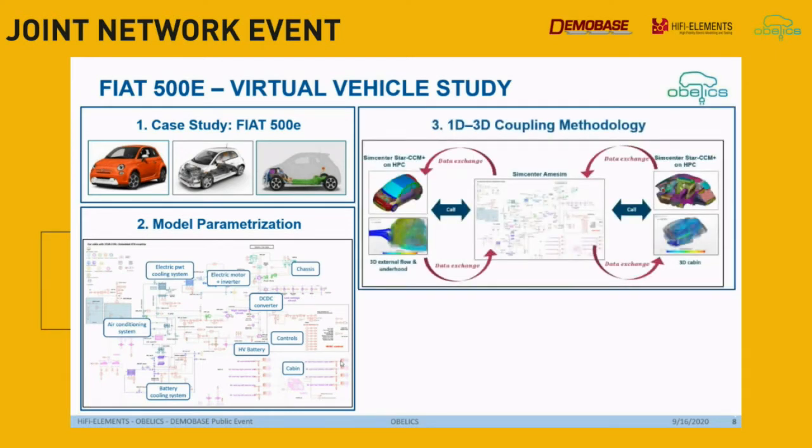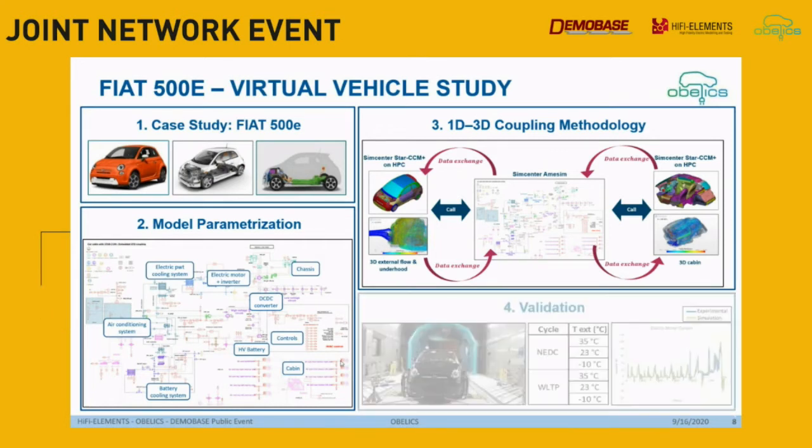Then a methodology was implemented to couple this 1D model to 3D CFD, computational fluid dynamics, models, in particular two, one for the external vehicle and one for the internal, using Star-CCM+. This was in order to obtain a higher fidelity simulation, in particular for thermal management.